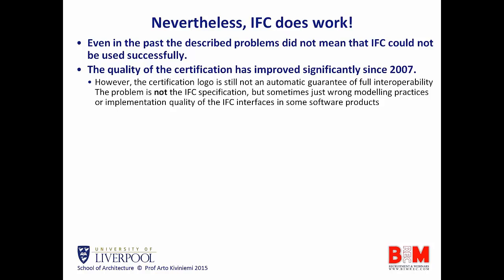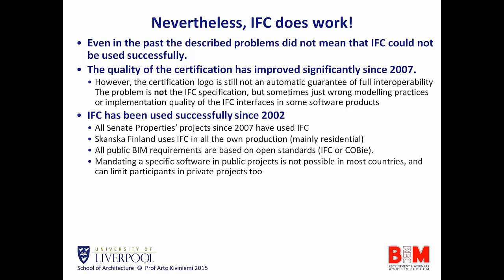As said, certification is now much better than it was. And when people are complaining that IFC is not good, it's usually not the problem of the IFC specification. It's actually quite good. Sometimes it's because people are modeling in the wrong way, and how you model also affects the quality of the IFC. And also sometimes the implementation quality of the IFC interfaces is not necessarily perfect in every software product. So there are still some problems, but as said, it's useful.